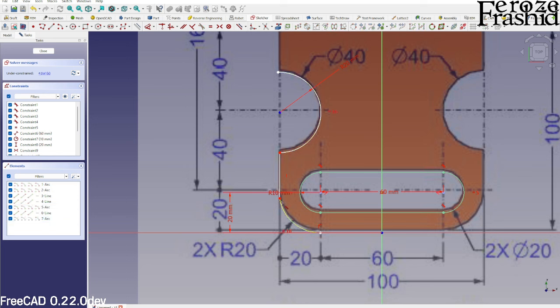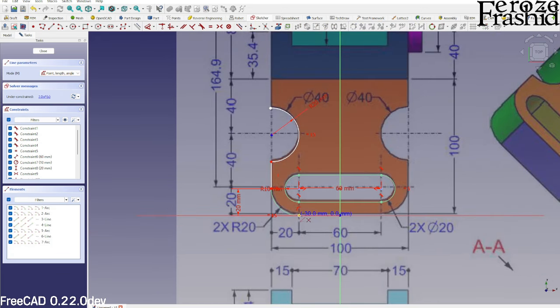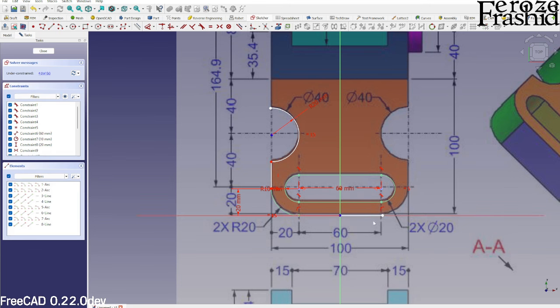And also here it will be tangential, so T on the keyboard, and then maybe draw a line. So that line is going to be 60. And I haven't drawn that actually. I'm going to go ahead and make this dimension 20. So this is 20, this is 20, makes it 40.